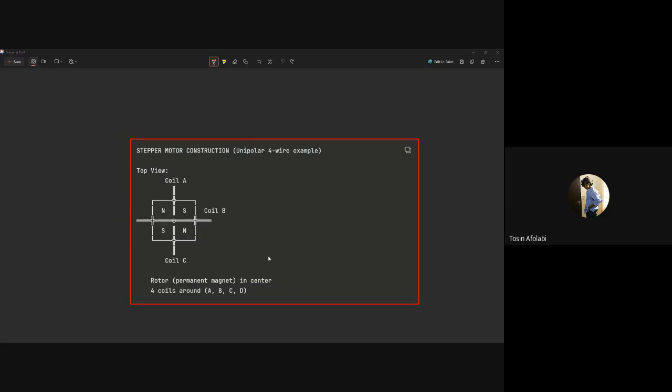It's simple to run at 40 frames, but because it's less frames, it's not going to be very smooth. It's the exact same thing with a full step, because you're using 4 steps per cycle at 1.8 degrees per step for a 200 step motor. It's very simple to execute, but it's going to be less smooth.